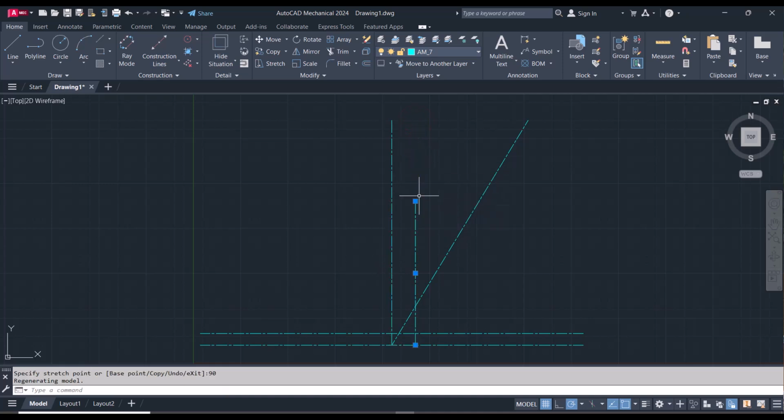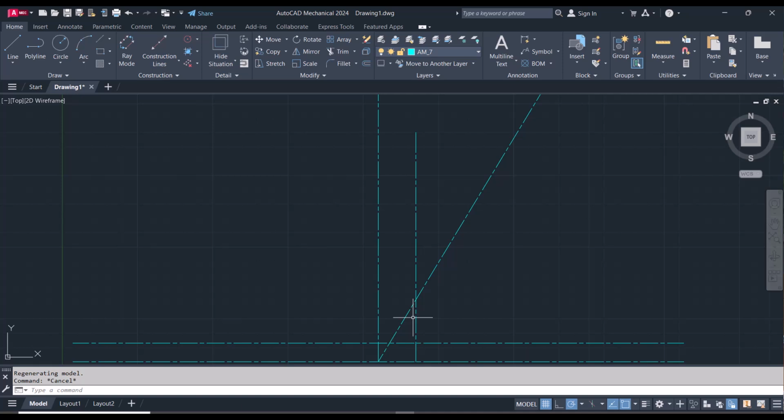I would click on it and then get this graph and minimize the height, maybe by 90. Now this intersection here is the center of some of the visible edges of the tangential curve. So here we have a circle. Let me switch the layer to 0. Let me choose the center diameter method, and this intersection is the center of the circle to be drawn.